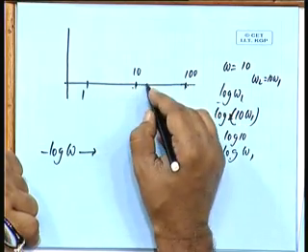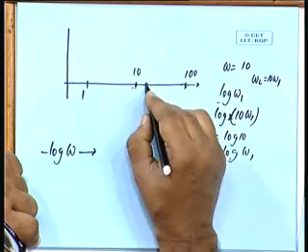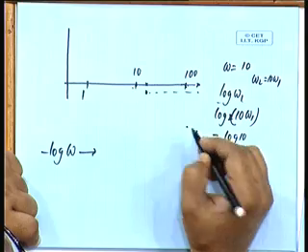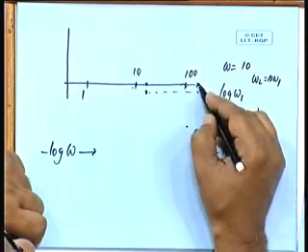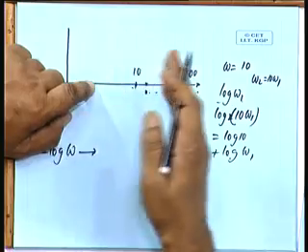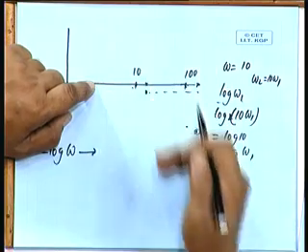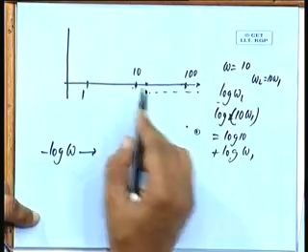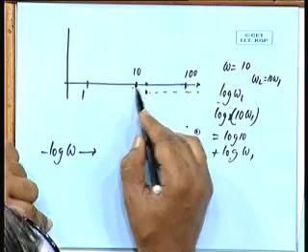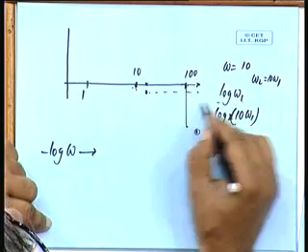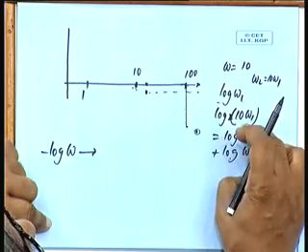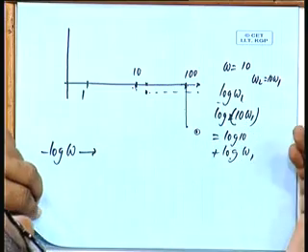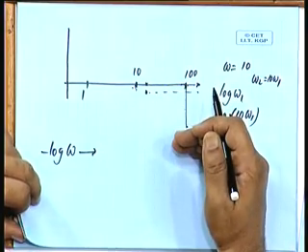It could have been any frequency. I can take, say, 12, then at 120, that is 10 times that frequency, whatever was the value, I will go down by 20 dB, that will be the new value of the function at 120. So, you take any frequency and 10 times that frequency, the jump will be by 20 dB. So, if I draw a line at omega equal to 10, in this example it was 1. So, at 100 it will be 20 dB, at 1000 it will be 40 dB, another additional 20 dB. So, at every decade, if I increase the frequency tenfold, I will always get a 20 dB additional term.